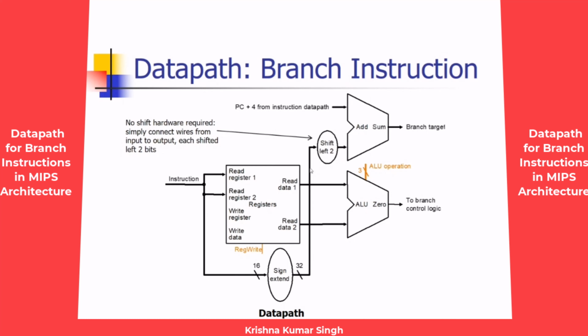So in order to compute the number of bytes again, we need to multiply this number of words by 4. This is performed by shifting left 2 times. And actually there isn't any hardware for this operation. You can easily connect the wires from the input to the output, each one shifted two bits to the left.